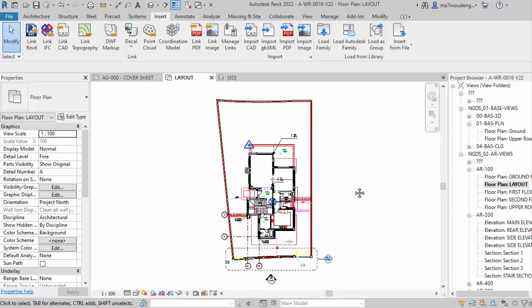So if you have a specific coordinate system that you want to work with, I'm talking now about a global coordinate system. For example, this project that we are seeing right now is in a coordinate system called Red Belt, Egypt Red Belt. You can check the first video to know more about that. But anyways, how can I reflect the coordinates inside Revit in the right way?